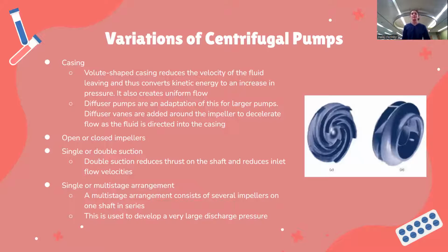You also have open or closed impellers, as shown on the right, single or double suction, and double suction reduces the thrust on the shaft and reduces inlet flow velocities.